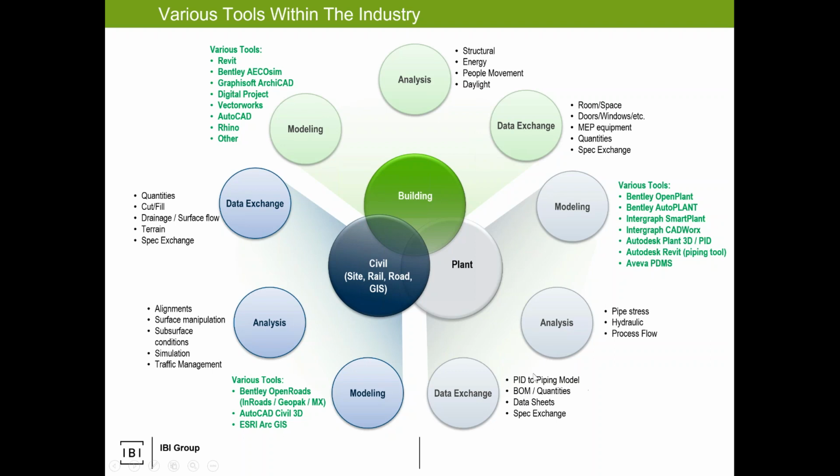And then this P&ID, process and instrumentation diagram. Those are the diagrams I showed earlier. That integration of saying, hey, I've got 5 valves and a tank and 5 pipelines in this one little schematic. Scan my piping models. Do I have those same 5 valves? Do they have the same name, the same particulars, the same stuff identified as flowing through them so that they analyze properly?